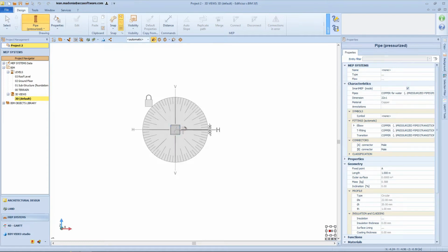The main angle snaps are represented by the X and Y axes, which identify the directions of the axes of the global reference system. They correspond to the angles 90 degrees and -90 degrees along the X-axis, and 0 degrees and 180 degrees along the Y-axis. From the starting point of the pipe, by moving the mouse towards the circumference of the goniometer, the secondary angle snaps identified by multiple angles of 45 degrees are intercepted. Then continuing with multiples of 15 degrees, and near the circumference also multiples of 5 degrees.